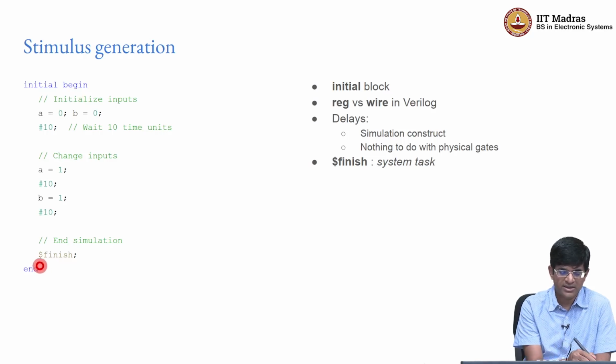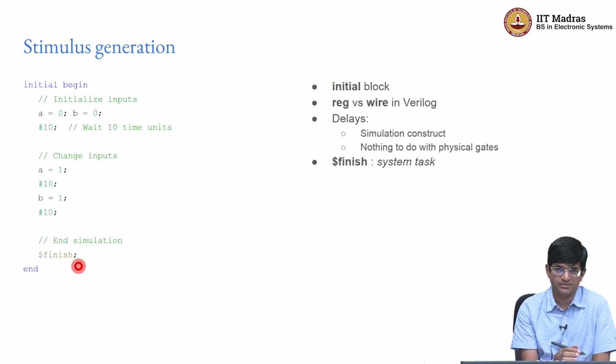But the bottom line is this $finish over here is what's called a system task. It's not directly a keyword of the language. It is something which tells the simulator, okay, finish up with the simulation, wind up everything and stop.